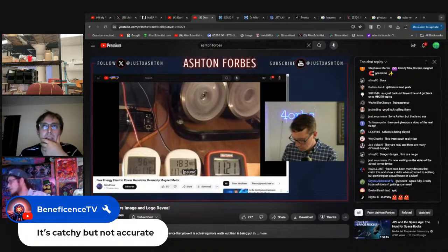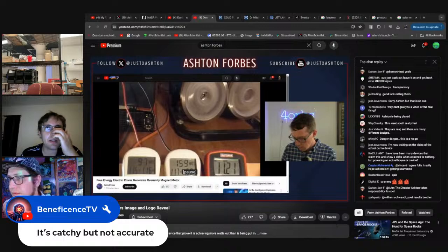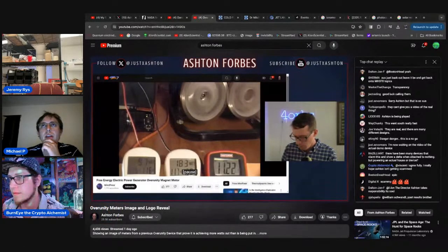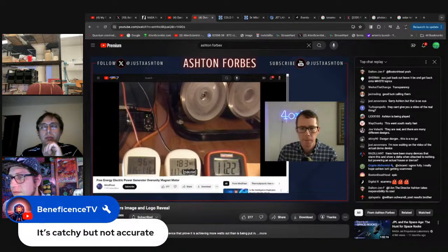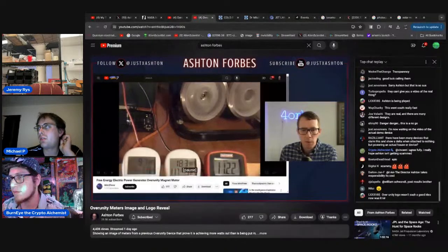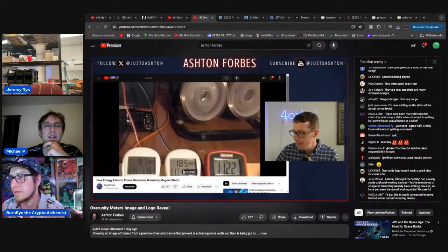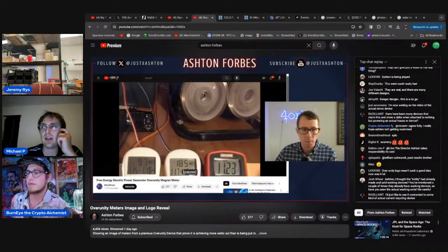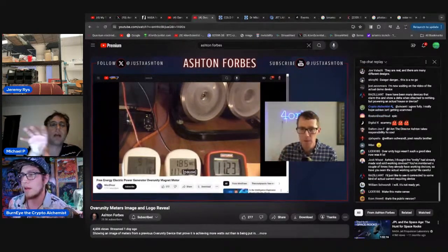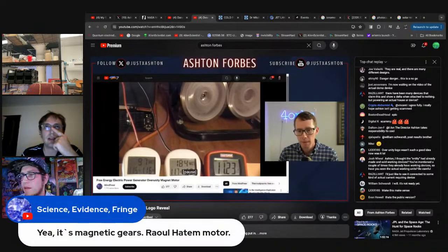But yeah, before we jump to that, it sounds like a lot of cool stuff there. One of the things I always see is if someone gets 130, 150, 170, up to 200% efficient, typically when it's in that range, it's just someone who is not familiar with power factor corrections for measuring power in electronic circuits. When you have the phases overlapping in different ways than the standard way, then there's some reactive power in there, not just the real power.